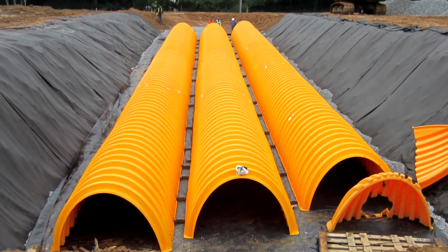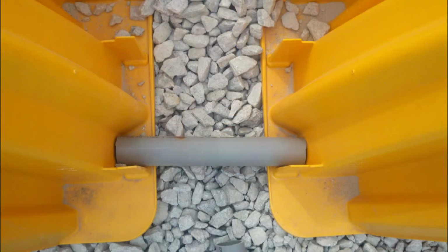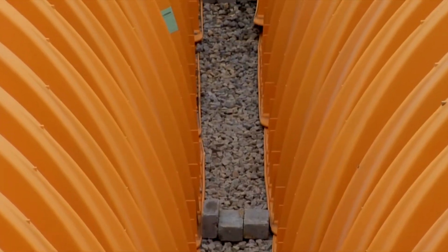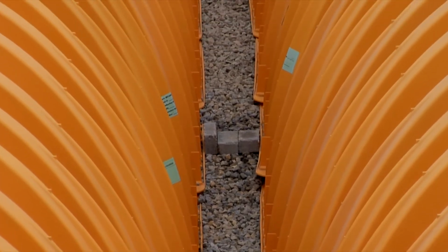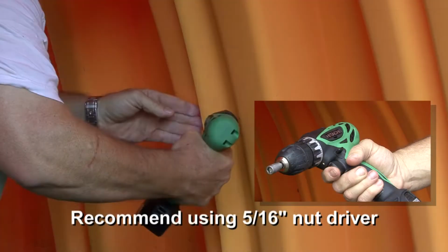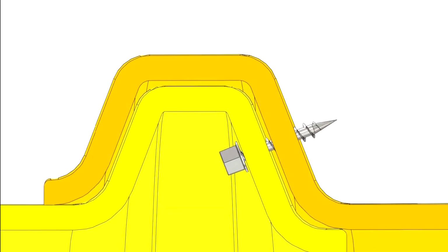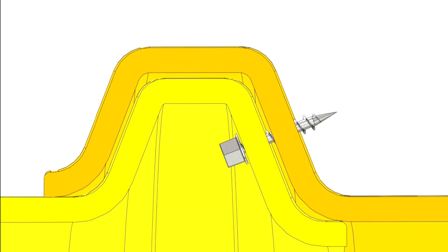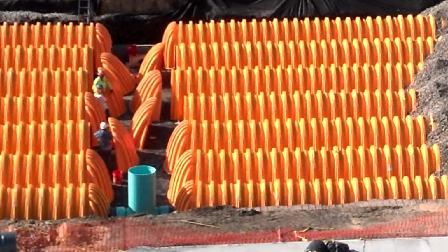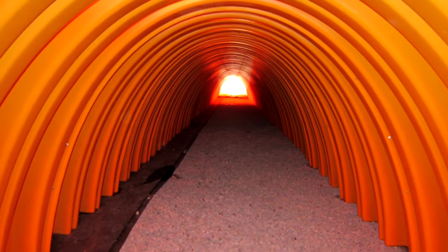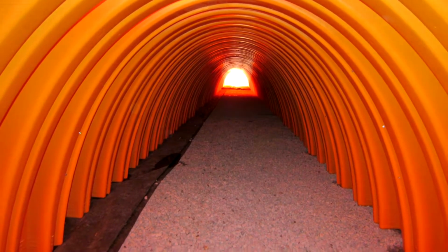In preparation for placing the chambers, a minimum 9 inches spacing must exist between chamber rows. Non-degradable spacers, such as brick, can be used for layout convenience. When placing the MC4500 chambers, a total of 6 screws must be used at each chamber joint, 3 on each side. The specific types and locations of screws to be used are detailed in the StormTech construction guide. It is recommended that the end caps be left off of either end of the rows until the correct placement of stone can be visually verified.